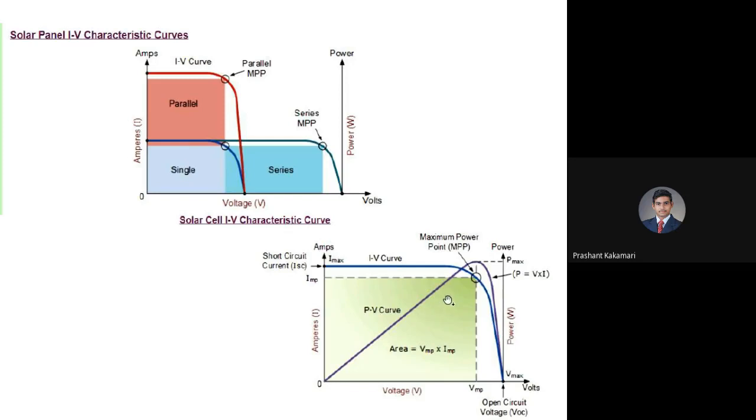Say for example, you are passing solar light of 1300 watt per meter square. All this 1300 watt per meter square is not converted by a meter square cell. If I take a 1 meter square cell, it is also not converting all the 1000 or 1300 watt of energy. It is converting very little. That shift in energy is shown here, the gap you can see. It depends upon the efficiency. So the maximum current or maximum voltage or the maximum power point of the cell, if you speak, is a little bit shifted inside.